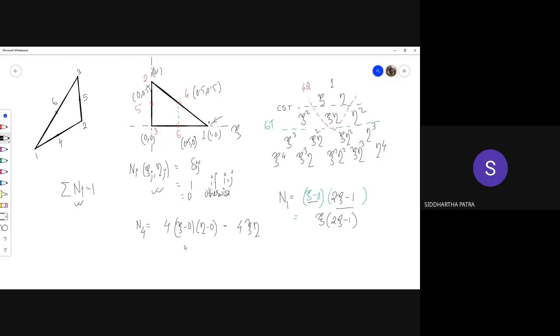So can you construct all the other shape functions? For example, can you tell me how much is N2? Or N3? N3 is going to be interesting because for N3 you are supposed to take the line 5 6 and line 1 2. So you'd see that each shape function has some term from their CST counterpart.